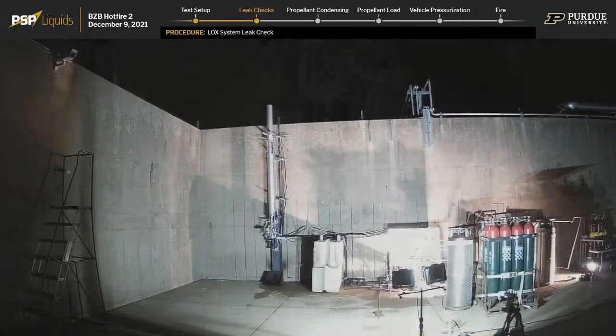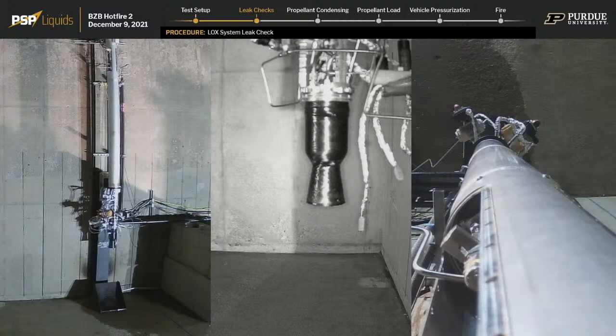Do we want to talk about one of the more interesting additions we have? Are you aware of the PSP Piccolo? Yes, the PSP Piccolo. On our first hot fire attempt, in addition to aborting, we had an anomalous methane fire in the lower engine bay, the lower airframe, as you can see on the stream. To resolve this problem, we've made a couple of changes. We're pressurizing the vehicle. We're waiting for PT-OXO1 to stabilize. Over. In addition to shielding all our wiring with foil to help prevent it from melting and severing critical data and valve connections, we have also installed a nitrogen blower that we have named the PS Piccolo to blow inert nitrogen gas into the lower airframe and prevent fires from forming.